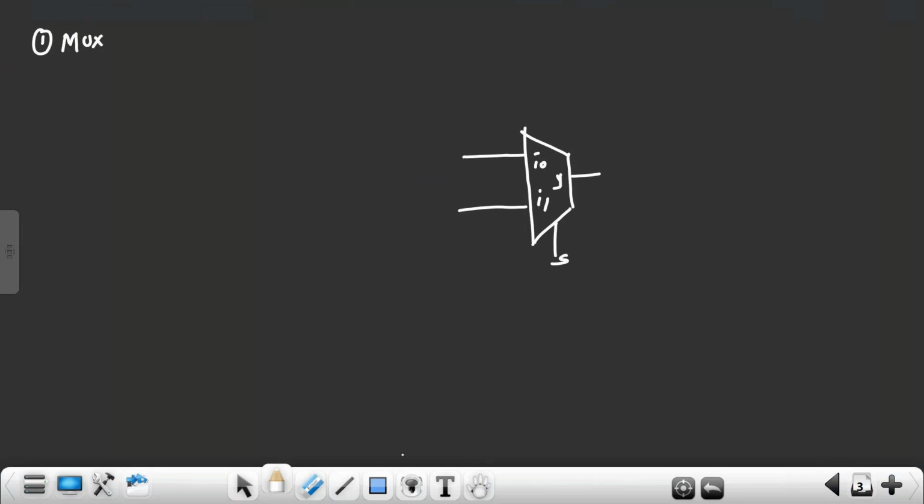Okay, no one can write. Or if you can write, okay, it's fine. But I will tell you its operation. Can you explain the behavior of this mux? Yes, I am getting the response. When the select line is 0, my y is going to take what? I0. If the select line is 1, my y is going to take what? I1. See, describing its behavior is easy, but describing its internal structure is very difficult.